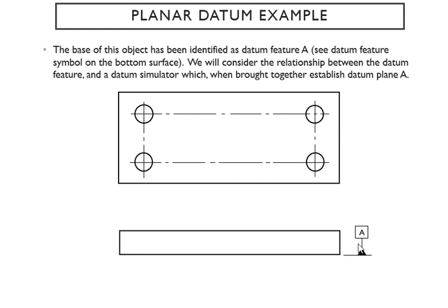It can be a point, a line, or a plane. Right now we're dealing with this base, so that's a datum plane, and this datum name is A. So if somebody says datum A, you know that. If your sheet says go ahead and draw a datum A on this surface, you should be able to do that using this symbol.